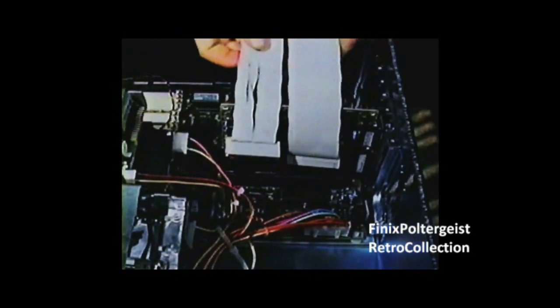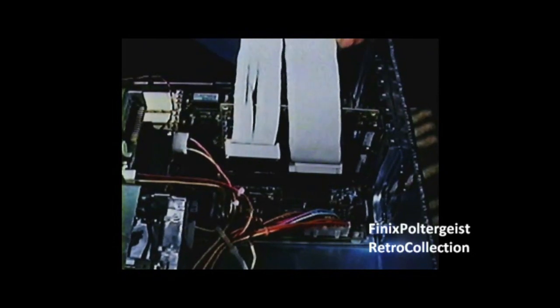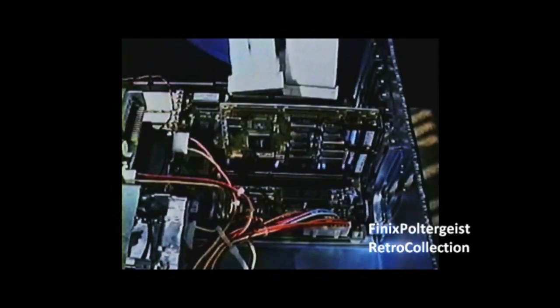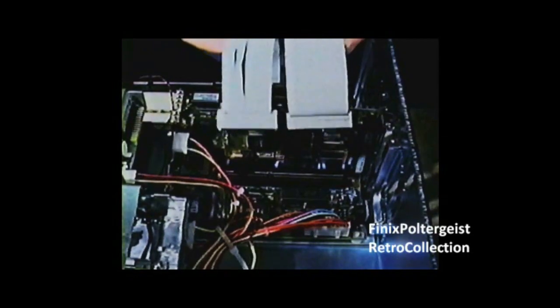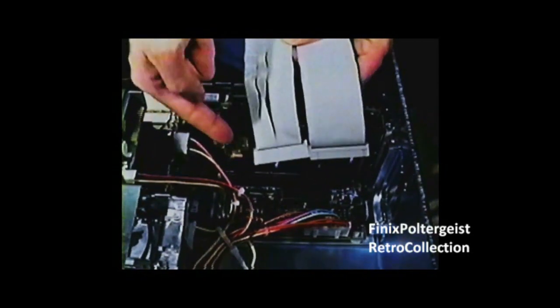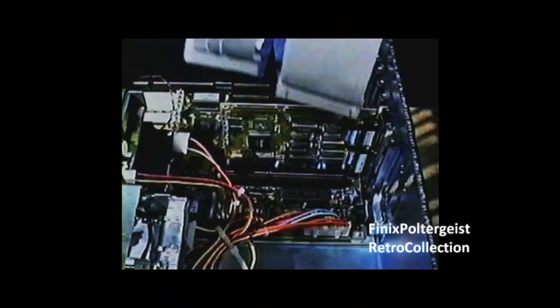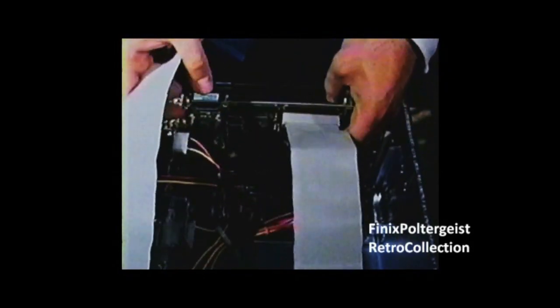Notice that there are two types of cables supplied with the controller, one for the hard drive and a different type for both floppies. The connecting pins on the card are labeled HD and FD for the hard and floppy drives respectively. Both cables have a red line running along the entire length of the edge. When plugging the cables to the card, make sure the edge of the cable with the red line is on the left or toward the front of both cables.